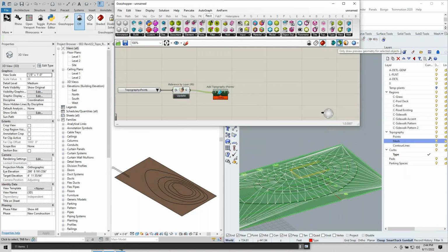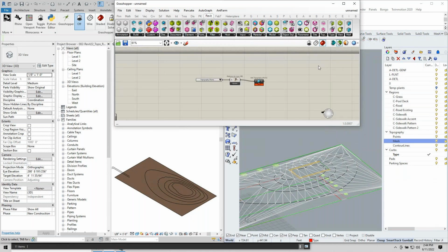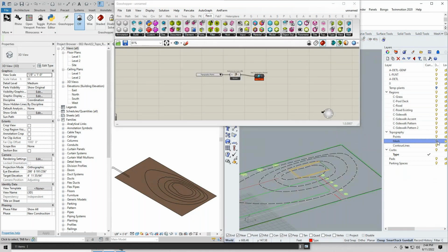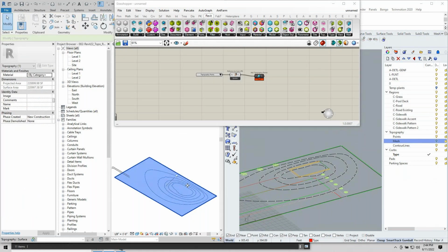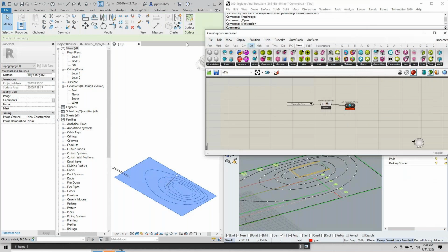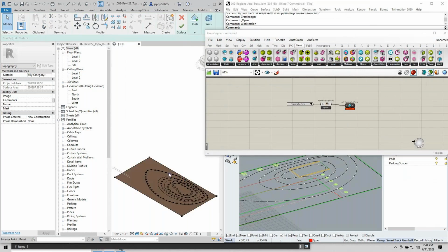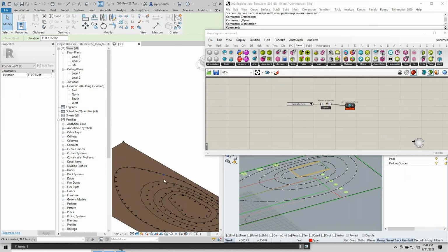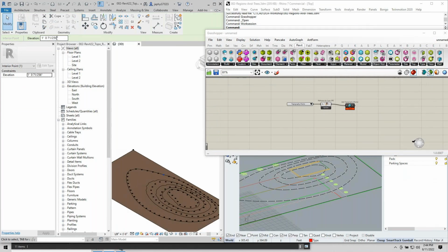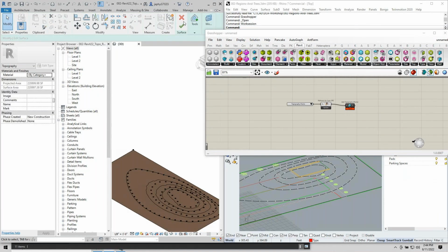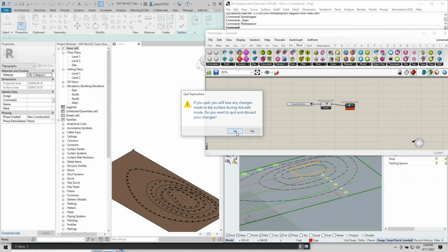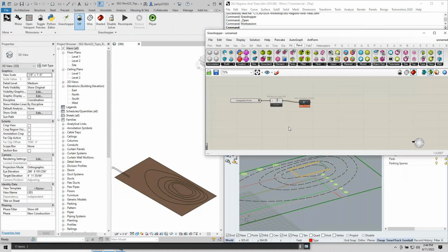You can use this preview geometry for selected objects only. But I'm going to turn off our mesh. Now that these points are in here, we have a topography that could be edited. I could change a point location manually, whereas if we were doing the mesh, you don't have that ability. That's a function of Revit.